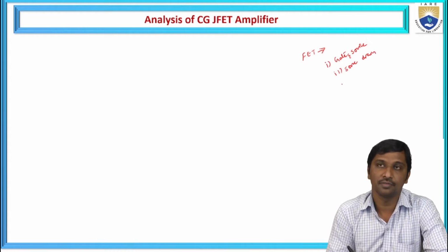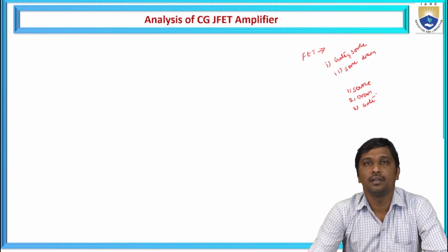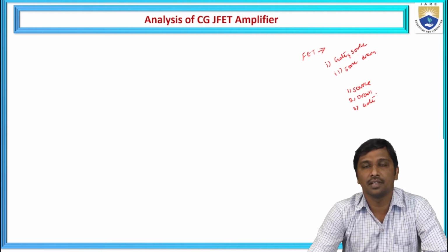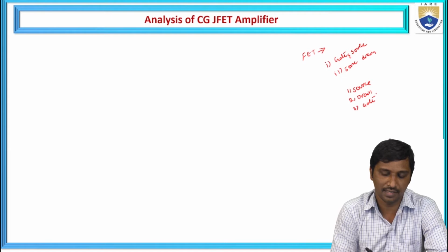If you observe the FET construction, we have three types of terminals. One is represented as the source, the second one is the drain, and the third one is the gate. Out of these three terminals, the source always gives the charge carriers to allow conduction in a field effect transistor. Based on the type of material used for the construction of the FET, we need to apply a biasing voltage between the gate and the source, as well as between the drain and the source.